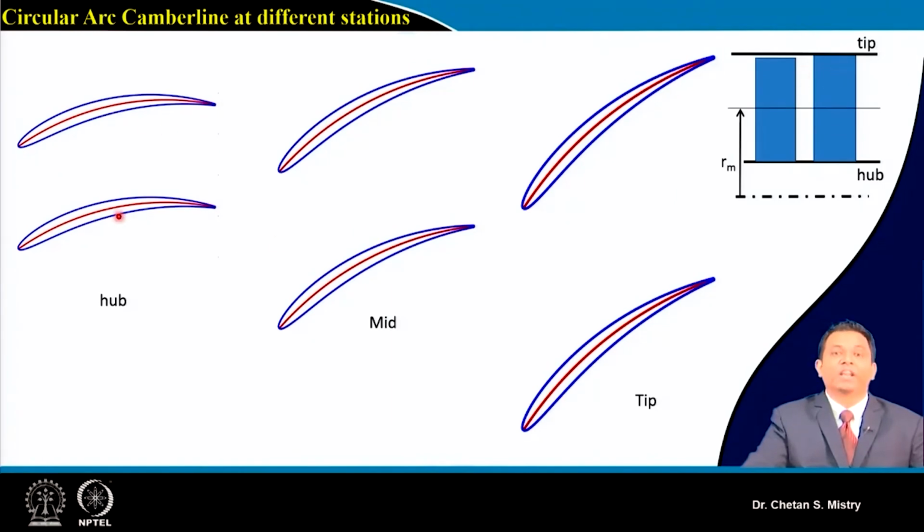For that configuration, for the rotor, I will have this kind of distribution. You can see we have a diffusing passage being made perfectly: at entry you have lower area, at exit you have higher area. The same here, and this represents the tip region. So you have a smooth distribution of thickness, and that gives you a smooth area passage, the blade-to-blade passage we are discussing.